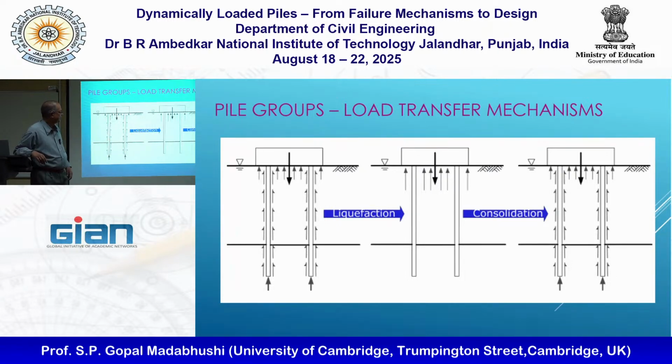So this is really where centrifuge testing can reveal the load carrying ability of piles and how the load is getting transferred to the soil. Now I know this is what's going on, I can design. All I need to do is to make sure that the pile cap has enough capacity, right? So maybe make the pile cap half a meter bigger in every direction. I'll have enough capacity.